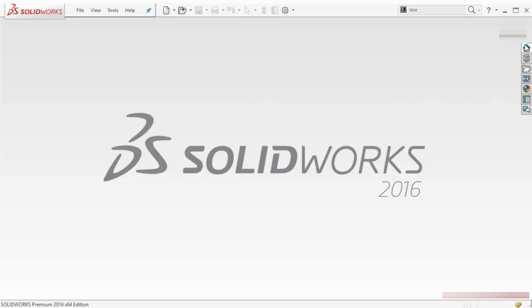This is by default when you will open the SolidWorks for the first time, or anytime if you open SolidWorks, it will show you at the right corner. Now if this does not show here, then you have to go to file. From here you have to make sure this task pane is selected, then it will show here.